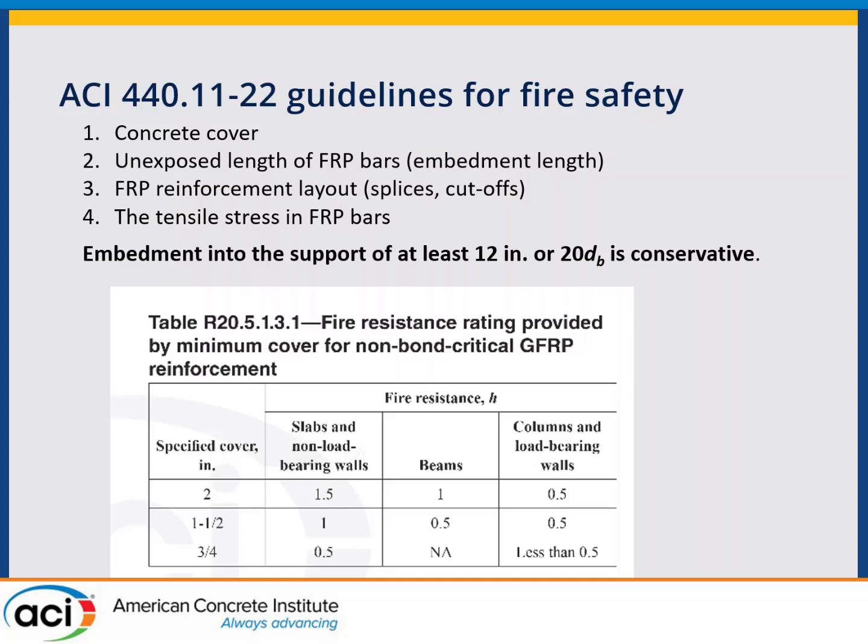Now, in those tests, the actual tests that we did, they survived for 3 hours, and they actually only failed when we increased the load. And to start with, I should mention, because I talked about the load, that the load that we applied was about double what we would ever have expected in service conditions based on service levels.